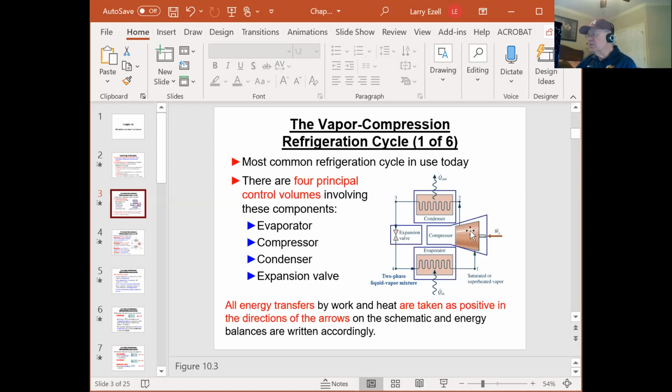When this system is running, what you're doing in a refrigeration system is sort of sucking up the heat from an area, and you're storing that heat in the vapor in the evaporator. And then you go through a compressor, and you're compressing it up and you increase the pressure and the temperature, as always.